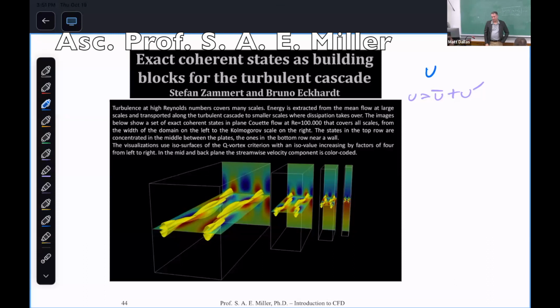So that's one technique. The other technique: the computational power is driven by the largest scale and the energy dissipation rate, and the smallest scale turbulence we need to resolve with grid points. Now, what if I could not worry about the smallest scale? What if I say, okay, the smallest scale is now 1,000 times bigger. So I'll use the computer to just simulate the big scales, and I will model with new equations that I create what happens to the small scales.